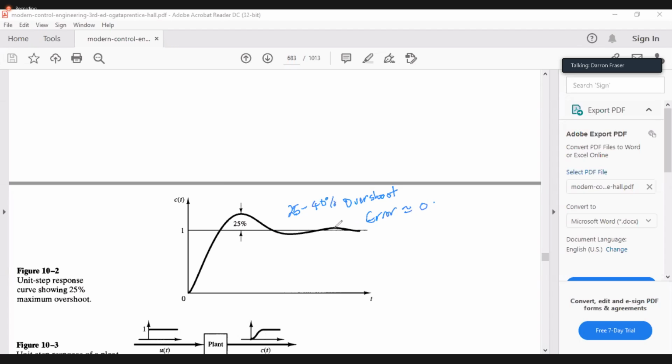We determined what was the length of time it's going to take to cycle. So with our TS and our TP and all those type of things. No, this method doesn't deal with that. It says that you're going to end up with 25 to 40% overshoot. It doesn't bother with cycling time, rise time, peak time, or any of those parameters.